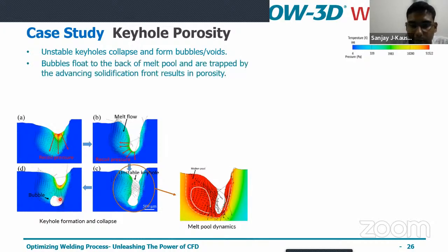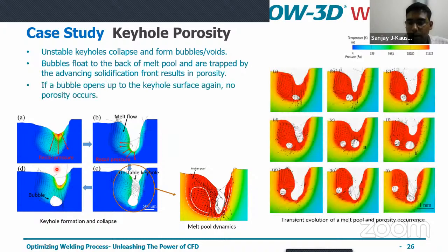So that is majorly because of the melt. Most of the bubbles, or some of the bubbles, tend to move up and go out of the melt pool, leaving a clear melt pool or clear bead. But sometimes what happens is, as the bubbles that are formed enter this vortex, which is actually a very high power vortex that circulates at a very high velocity, some of them end up not getting out of the melt pool.